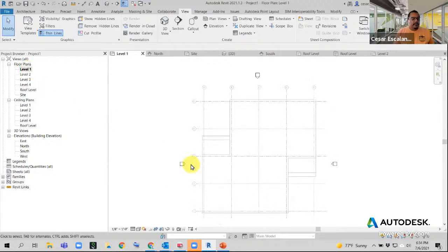And so we do this a lot with templates and link files. You're usually going to receive a file from structural. There is information in the structure that you don't need to display, and vice versa. The structural engineers require certain geometry from the architectural model. They don't need everything about the Revit model, especially finishes and things like that. And then they switch off, using the templates, the visibility contained by that link.